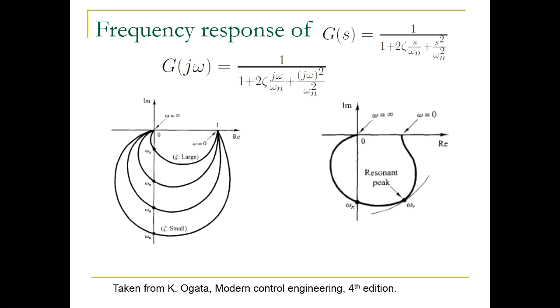So basically, what does that mean? You can have, let's say, a chandelier in a church or something. There is a gust of wind, but it's periodic. Very little force, very small force, but that can cause very, very big oscillations when the input frequency is very close to the natural frequency, right?